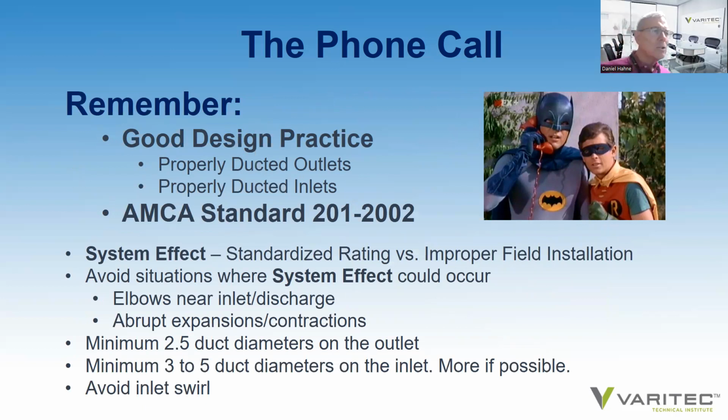Apply standard 201, lean on your fan performance curves as prescribed by AMCA 210 and how they're generated, and make sure that you maximize the straight duct lengths at the inlet or the outlet of a fan.